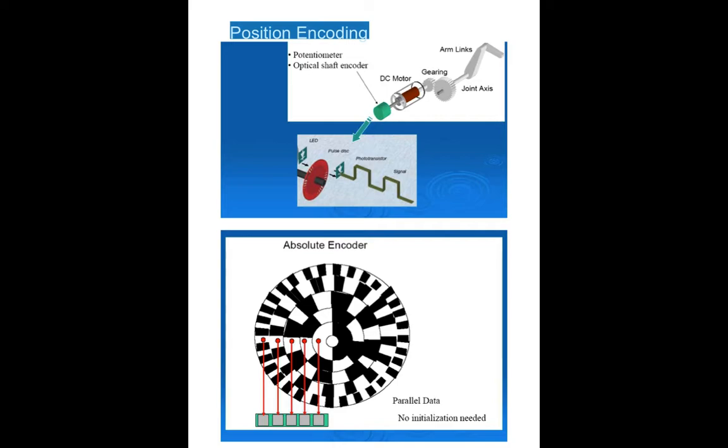We are supposed to understand how it is rotating, whether in a clockwise or an anti-clockwise direction. At the same time, we are supposed to understand the home position of an actuator. For a rotary actuator, we should understand where exactly it is situated.